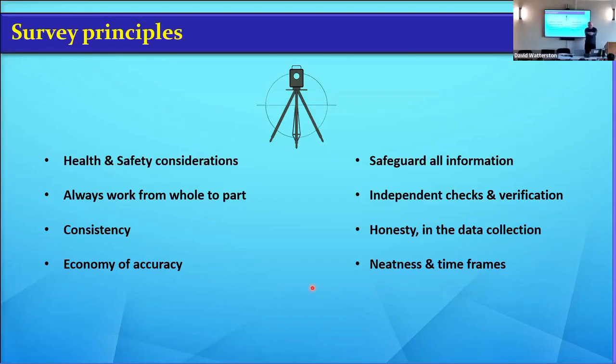So I went over because she was going like this with the staff. And I said, what are you doing? She goes, I'm trying to get the bubble in the middle. I said, well, it's never going to go like that. You need to move it really slowly so you can find out where the bubble's going. And again, in the new year, you'll understand when we're leveling and we're using the staff to take the levels, that it needs to be vertical.